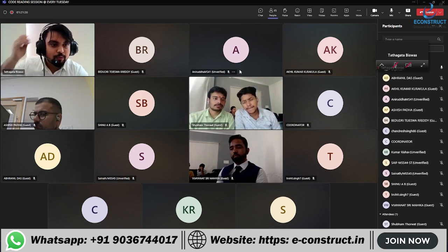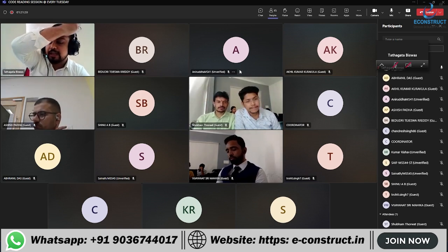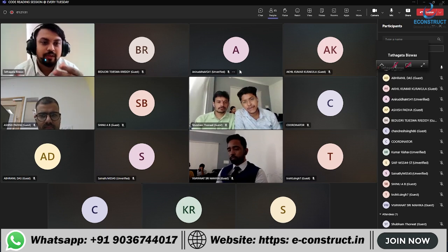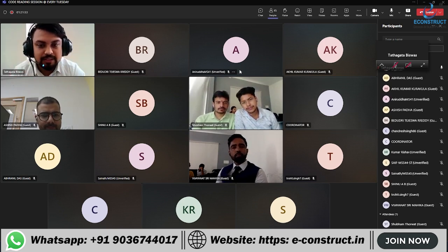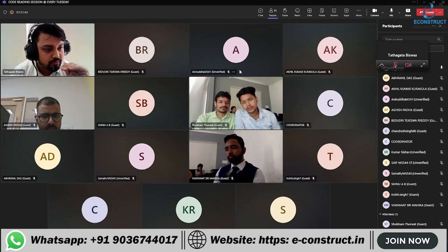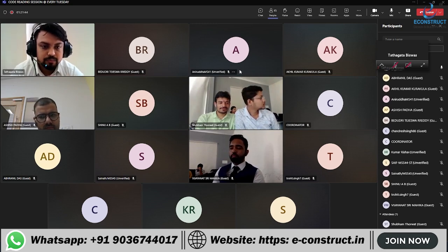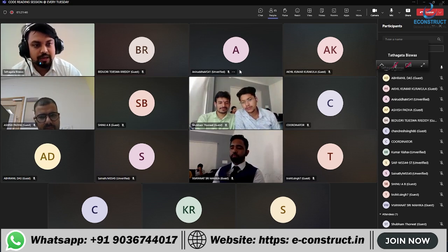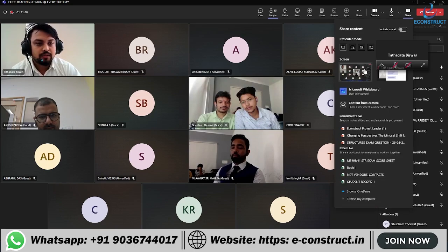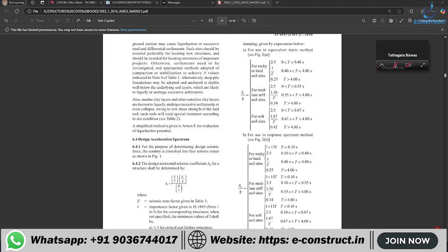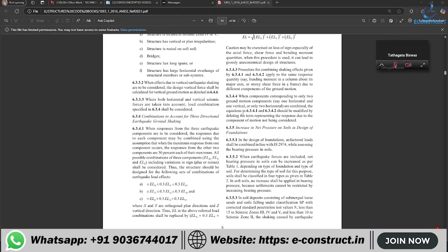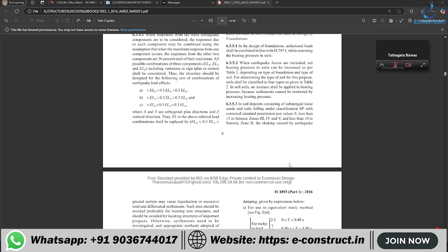So if a geotech consultant or any specialist finds rock and stops, and after that doesn't go further, don't make this kind of mistake. Even wherever you are resting the foundation, check the layers below that also. Understood? So that way. I think the rest of the things are self-explanatory regarding the different net pressure in soil, foundation and other areas.